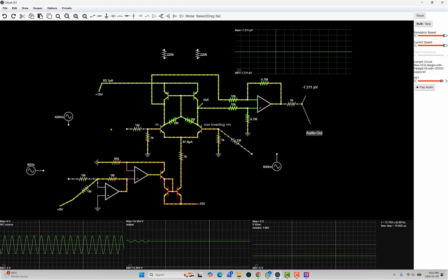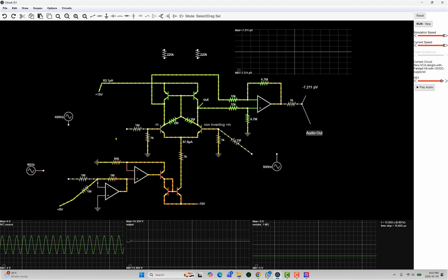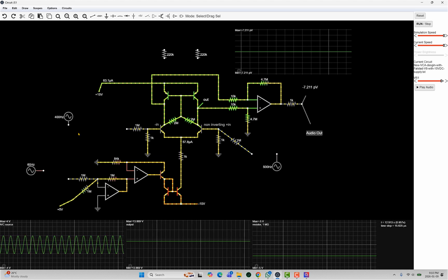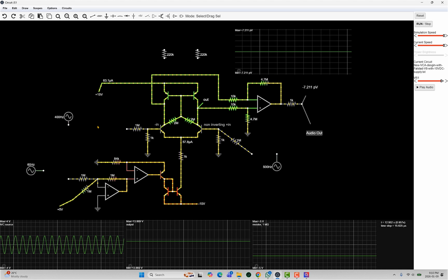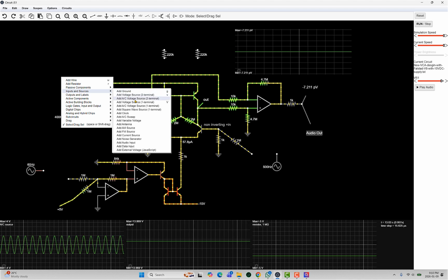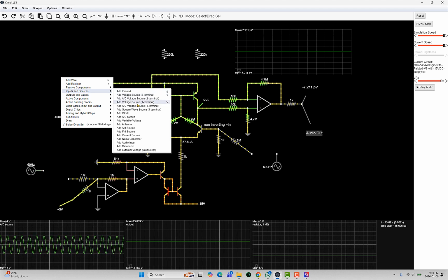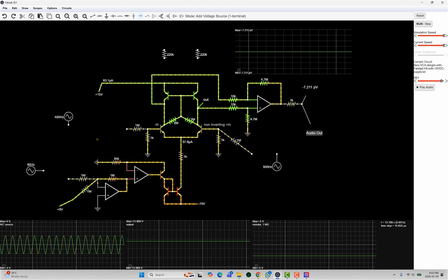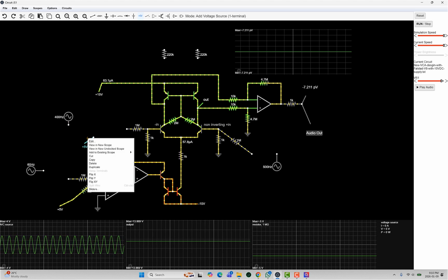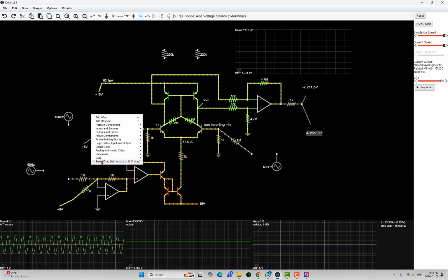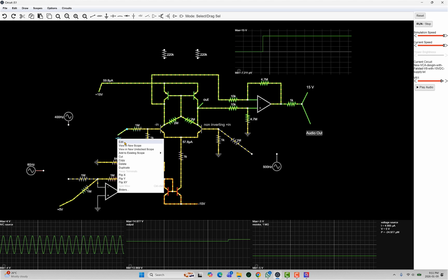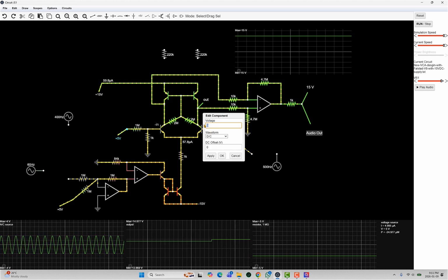That's what we want. Now, obviously, I could put an input signal here, and then we would get something different, right? So let's say I had a DC signal. Let me get a DC signal. DC, I don't want AC, add a voltage source. Yeah, this is right. Let's go like this here. And I'm going to move it in here and connect it to the input. So now I've got DC, but this is too high. Okay, I am going to put it about 1 volt.